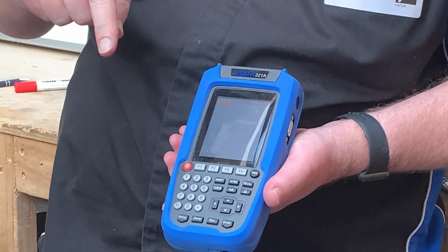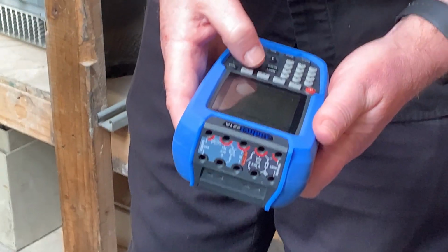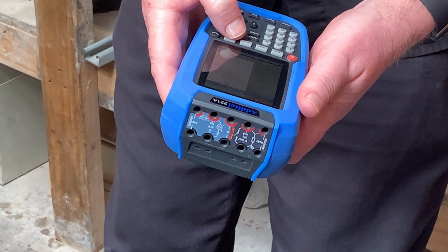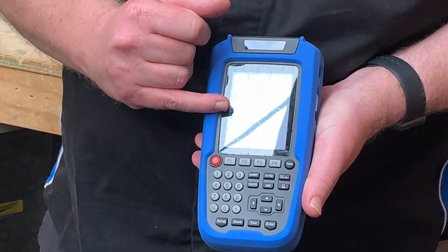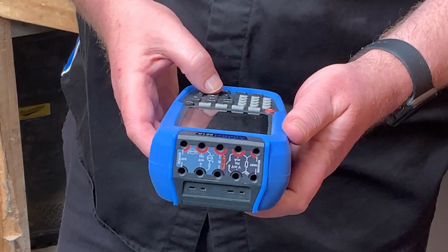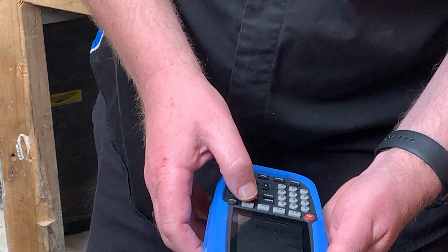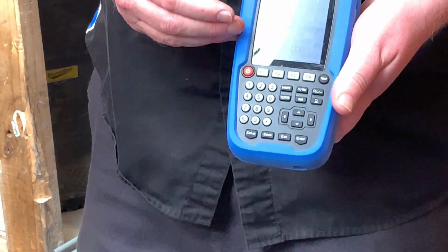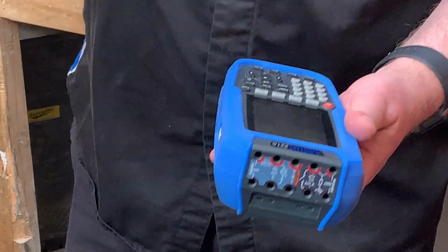It would produce a graph. So let's say we will do that. We'll do the calibration. We'll go select that, and we'll do an as found test. In this case, the instrument's producing a 4 milliamp signal, and you're going to type in what you see. Okay, we're getting 3.994. We'll accept that.